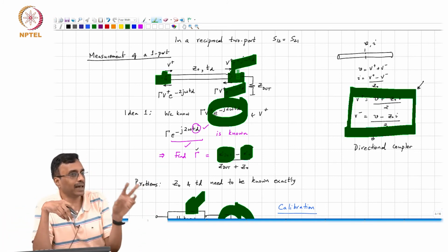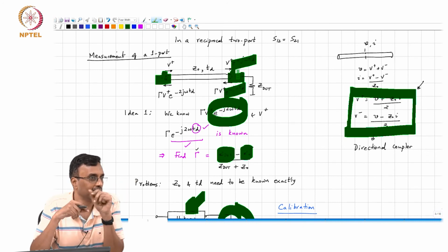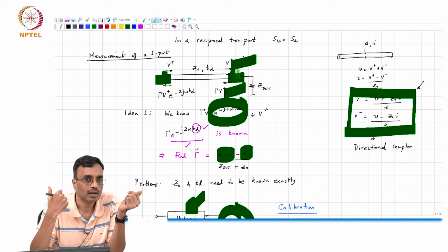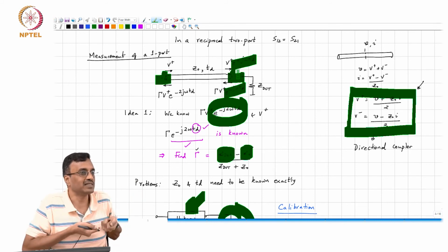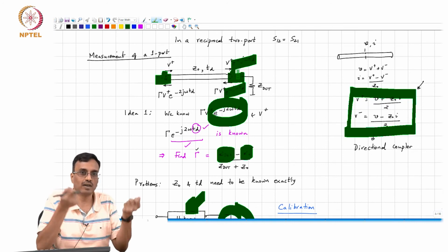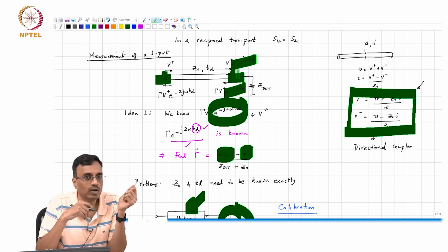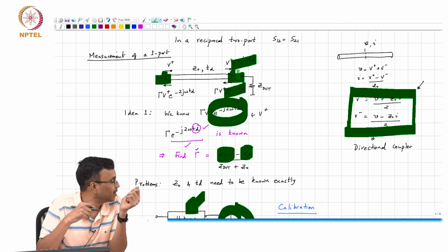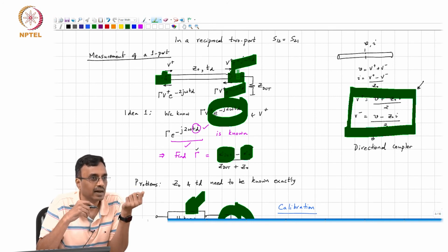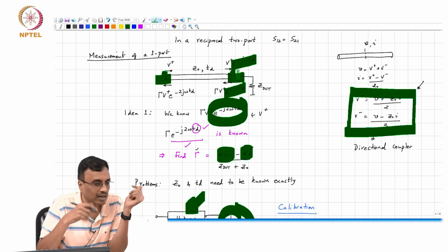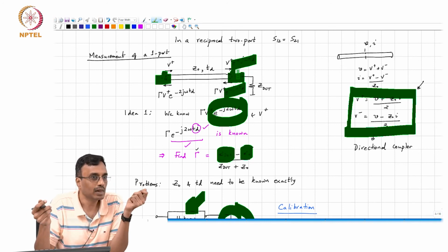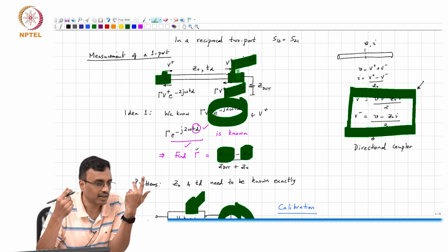Only when that omega times Td product becomes large do you start to have errors in measurement. If you simply stick a cable in and say, oh, I will continue to do what I did in my basic electronics lab, where everything was running at half a kilohertz, and I try to do this at say a gigahertz, then if you have a foot long cable, a foot long cable has a Td of how many seconds?